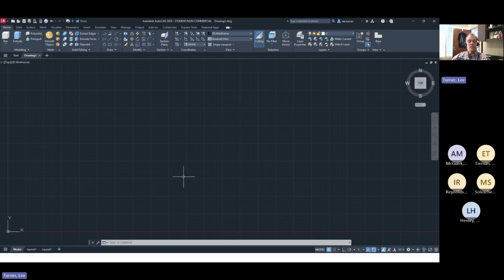But if you're using the keyboard to type, then that still works the same. No need to change anything. You might just learn some of the shortcut keystrokes for some of the 3D modeling commands. And if we keep going over here, you're like, well, where did my layers go? Usually they're right here. Well, if you come over here to the right, you've got your layer control still, but it just moved on you.